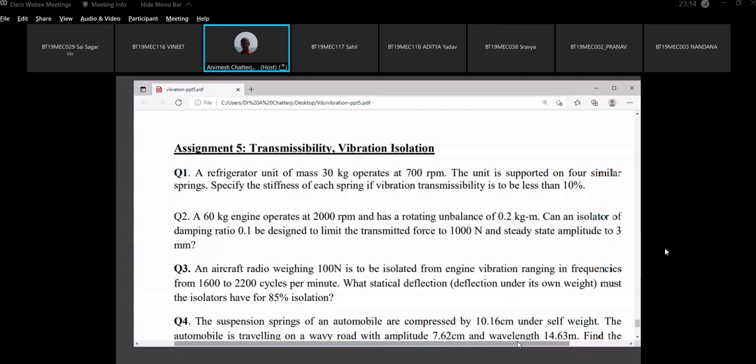So this shows that as an engineer, you can go to the market and buy the right kind of isolator spring. If it is a helical spring, you only have to specify stiffness. Damping you cannot specify because damping cannot vary. It is standard 1% or 2%, and we don't look for damping basically. Transmissibility less than 1 means we don't look for damping at all.